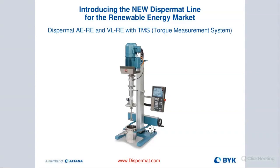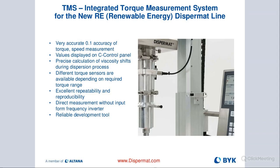And we actually included a specific torque measurement sensor that measures the exact torque on the shaft separately, not from the frequency inverter like it's usually done, which is not as precise. So we can get a really accurate reading of our torque, which is an indirect measurement of our viscosity in real time during the actual dispersing or milling process. So we have a really tight accuracy of 0.1 on the torque.